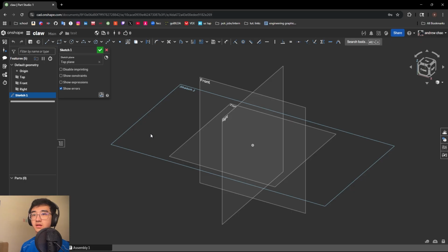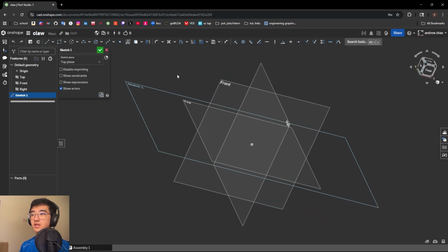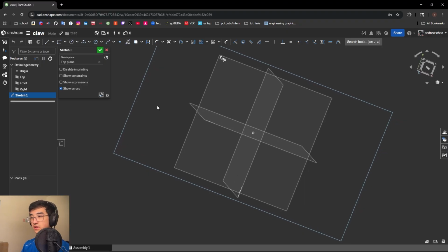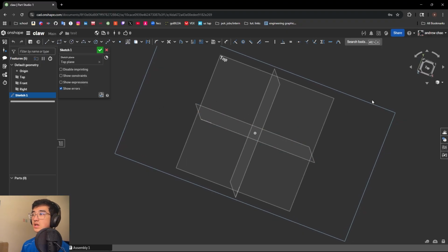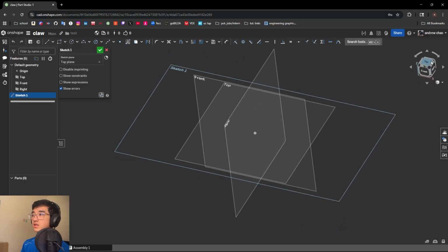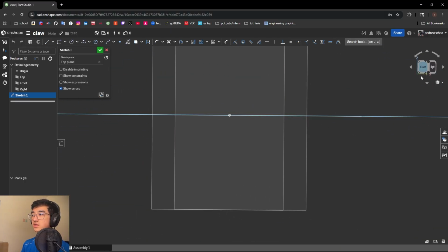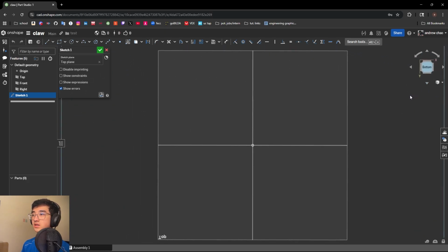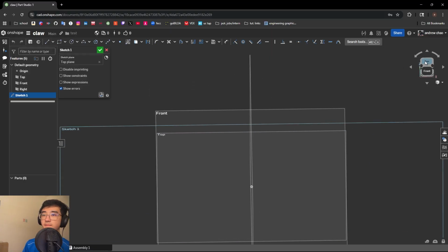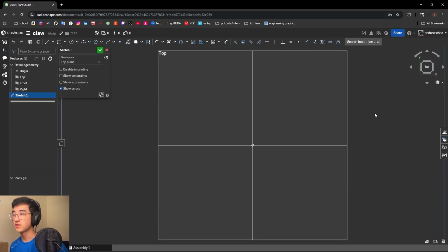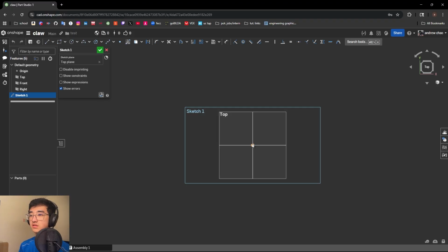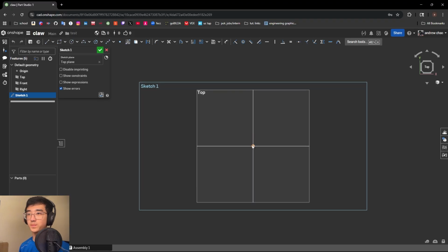And then you can use right click and drag to reorient your point of view so that it's focused on just the top. Or you can click on a face on the cube over here and it'll take you to it. So if you want to do front, you'll click the front, right, bottom, and so on. So we want the top. And as you go on, you'll probably discover some shortcuts. For example, you can press N and it'll immediately take you to the top down POV.